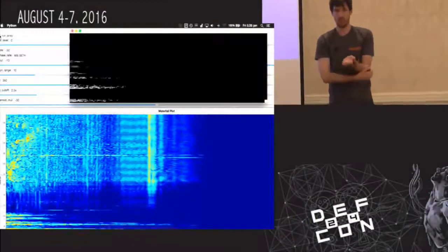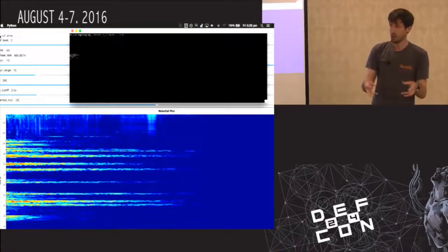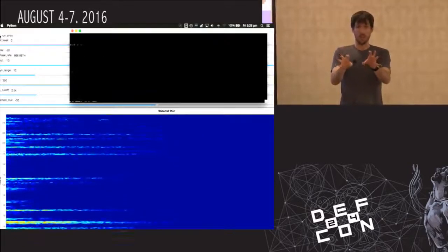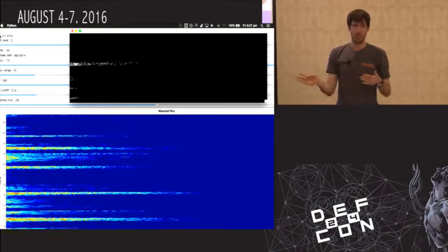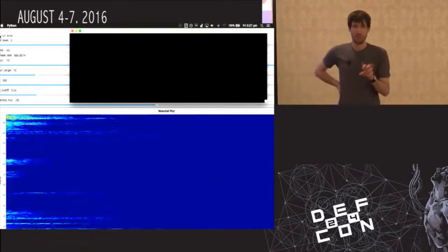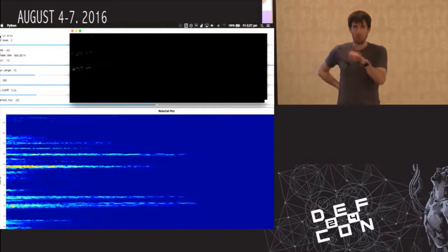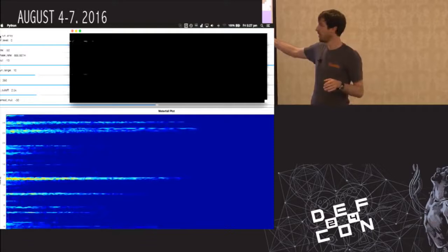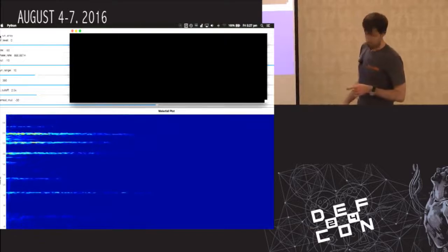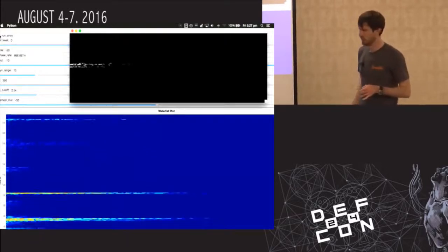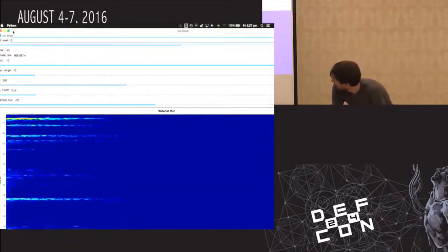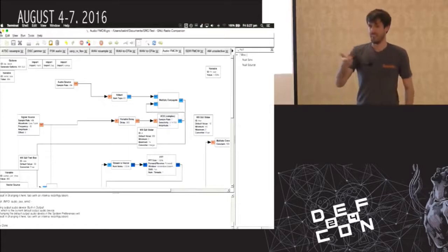But again, that's just super simple with this. What's nice is that you can get a USRP, like a B210 or something with two coherent outputs, get some cans, point them somewhere, and then get this to do exactly the same thing, but in the RF domain. And you can do FMCW and look at Doppler shifts. So you can do normal CW and just look at Doppler shifts. But if you use FMCW, then you can do this phasing and also get range information out of it too, quite effectively. And I started doing it very quickly at the end of one cyber spectrum with some cans, but I think I was getting overruns and stuff. But again, maybe for GNU Radio conference.